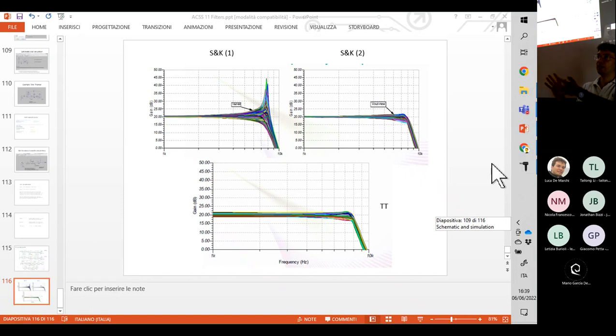This can be done with vibration sensors, because, for example, bridges or rail tracks have some characteristic vibration mechanism which can be compromised when a defect occurs. So by tracking the vibration modes of these components, you can infer the health status of the structure.